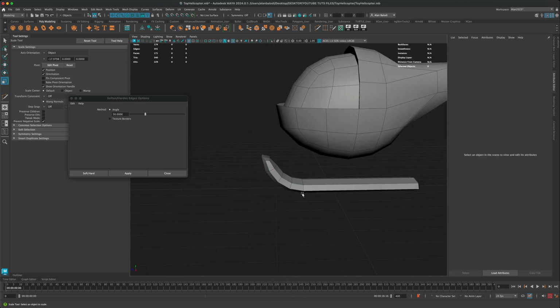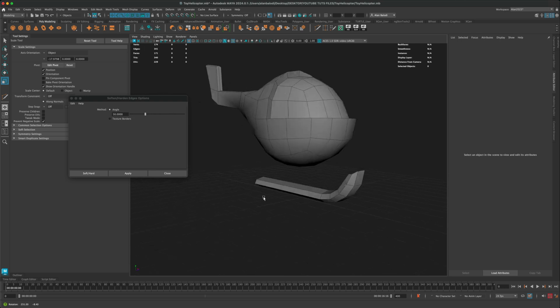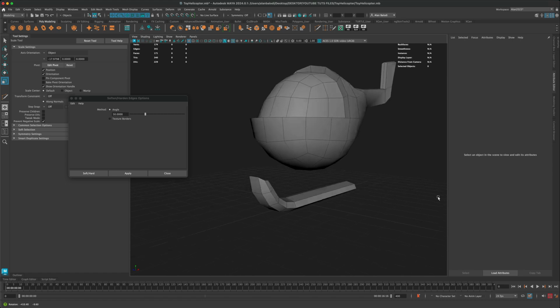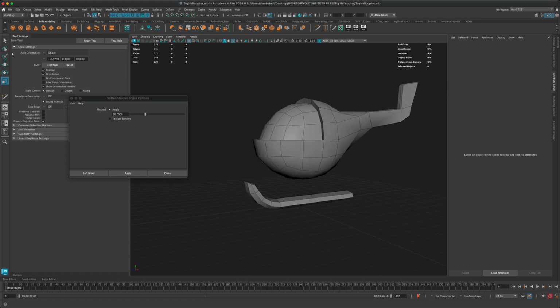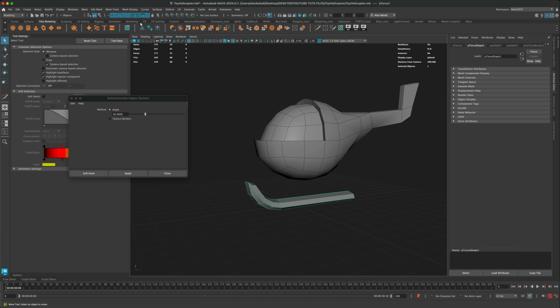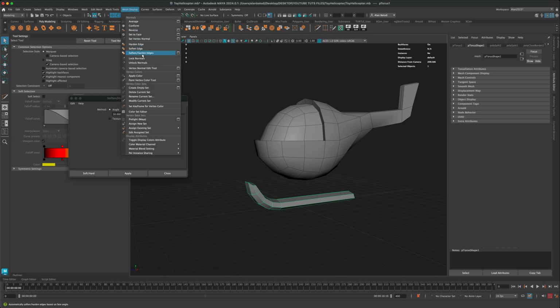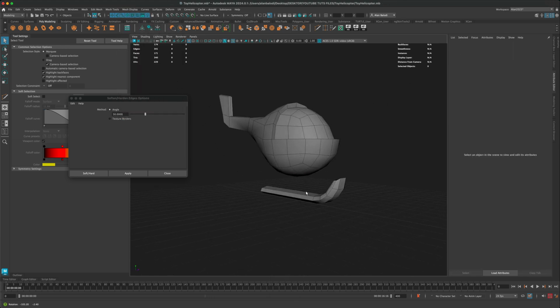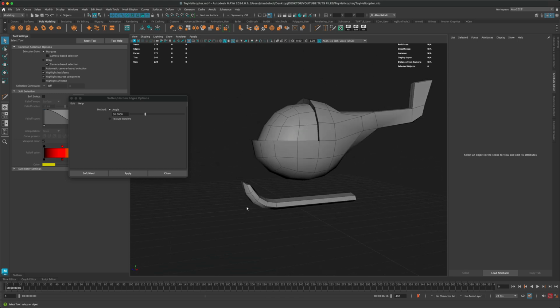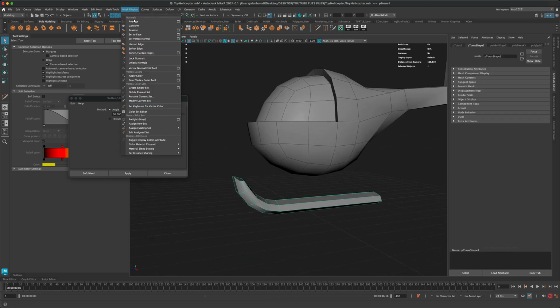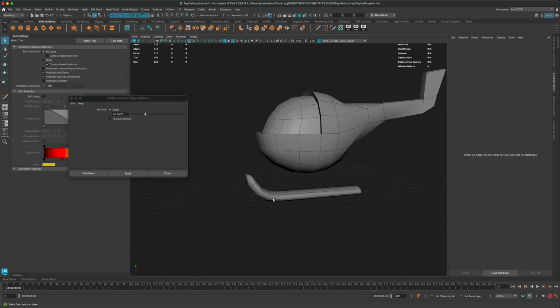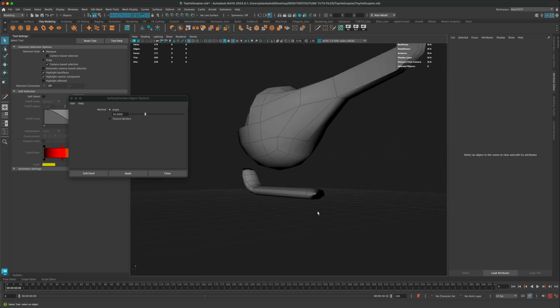One of the things I like to do when I model is I always spin around and make sure that it looks good from every perspective, every angle, right? So that looks really nice. Again, we can select this and go to Mesh Display and do a soften and harden edges. Remember, it's set to 50 degrees, so you have to make sure that you like what you're seeing and it makes sense. If you don't, you can also try soft edges and see if that feels a little better. Maybe in this case, applying soft edges makes more sense.